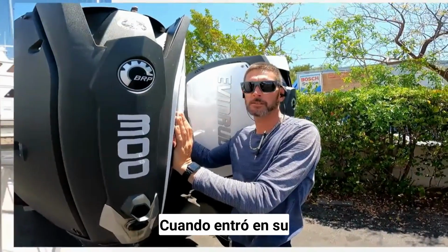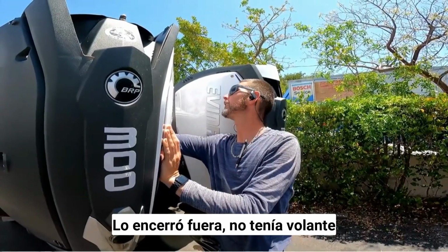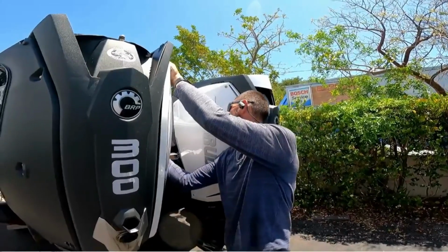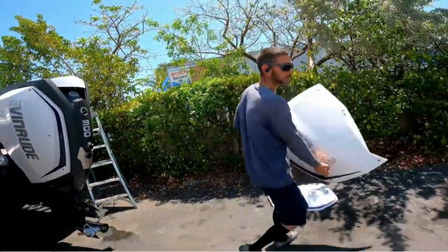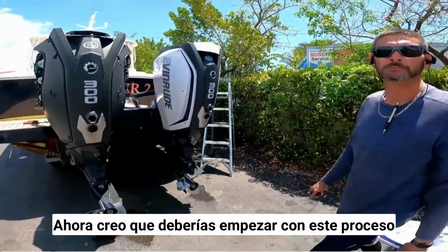He's complaining that when he goes into his joystick steering, he's getting a code and it locks him out, and he has no steering at that point. And you are suspicious about what? It's either going to be a chafed harness or a bad solenoid valve. Directional valve. Yeah. And now I think that you start with the process of elimination.